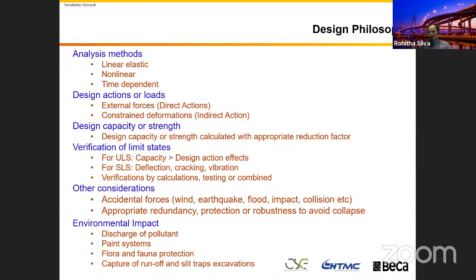For example, when you design buildings, you make sure your deflection limits are like L over 300. But when you design a bridge, your deflection limits go as large as L over 800 to L over 1000, to make sure of the deflection and vibration, because in most bridge design we are not doing vibration analysis. My experience is it's very difficult to predict that one. Even if you predict, it's not going to work that way.